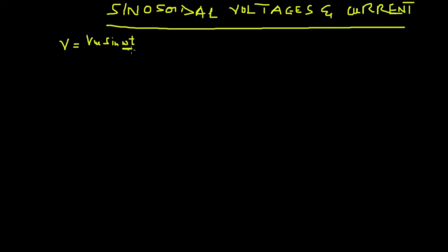It's not normally pronounced as Wt, but it can be further simplified into 2 pi f, so omega equals 2 pi f. Keep this in mind, sometimes you meet questions where you need to derive these formulas. So it could be written as V equals Vm sine of 2 pi f, and then you bring your t.